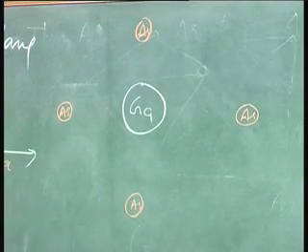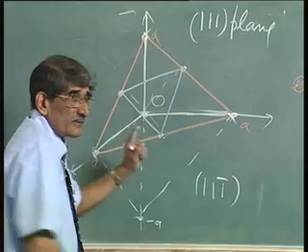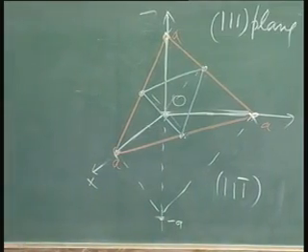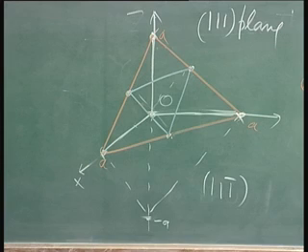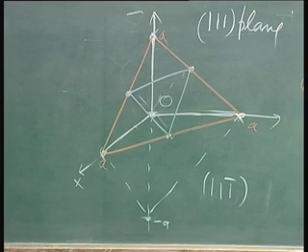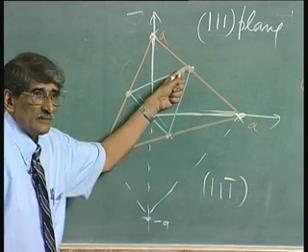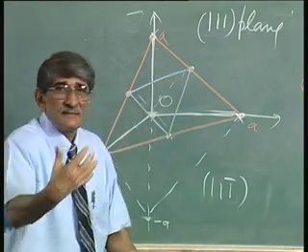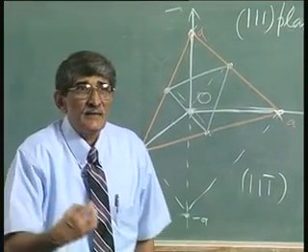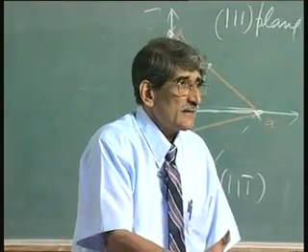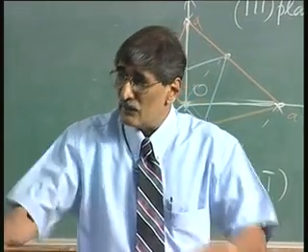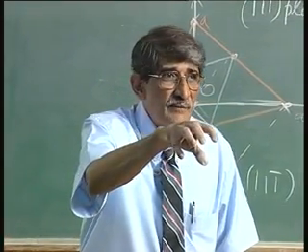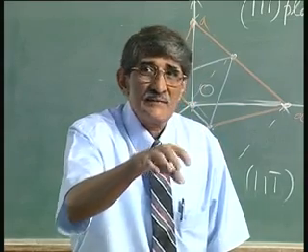So, this is the one which forms these 4 neighbors. Just go back to this gallium atom sitting here, bonding with that atom, that atom, that atom and that, and those atoms are in that plane. The corner one, this is at the corner. So, these together form the tetrahedron. When you say the crystal structure is tetrahedron, what you have done is gone into this cubic cell and picked out those neighbors which form the covalent bond together. So, that is the tetrahedron structure.